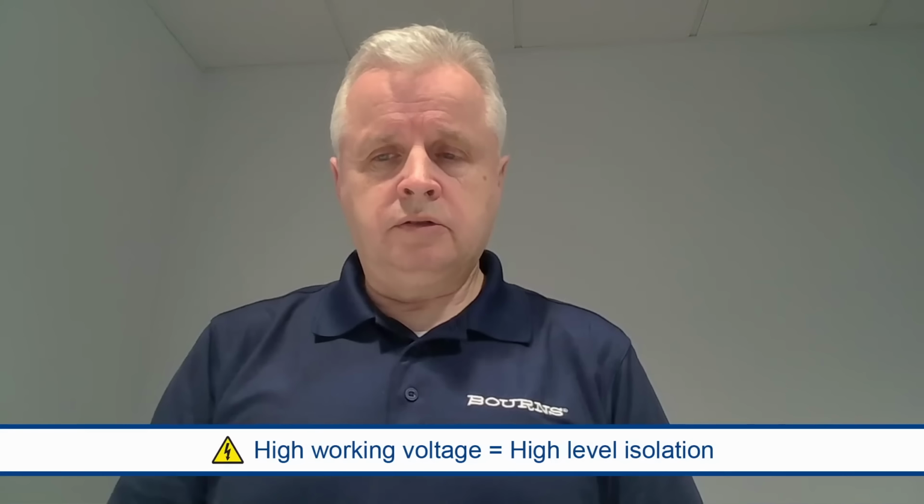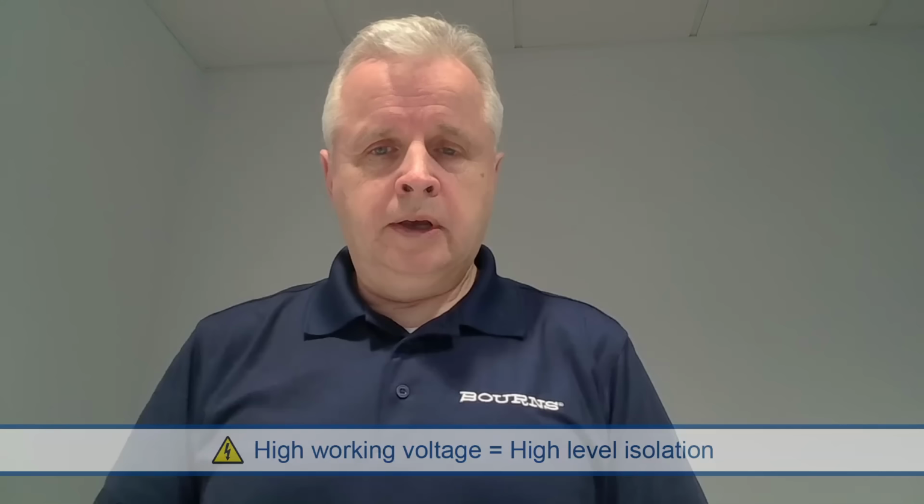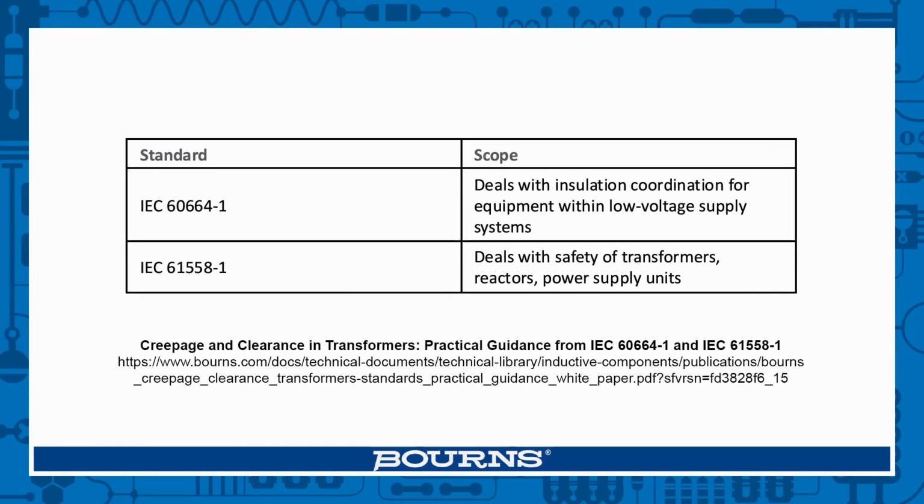So you need to be sure that you have a high level of isolation so that there's no risk of any electric shocks on the digital side. And when you're talking about working voltages of 1,000 volts or 1,500 volts, the isolation requirements get a lot more difficult. So that does introduce some complexity. You do need a transformer with very good isolation to provide those voltages, whereas maybe in the past you didn't need a transformer isolated converter. Now you do.